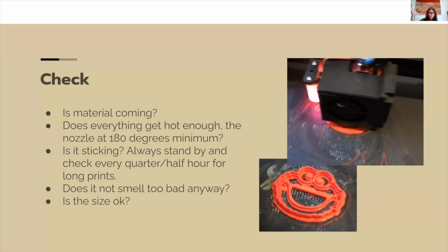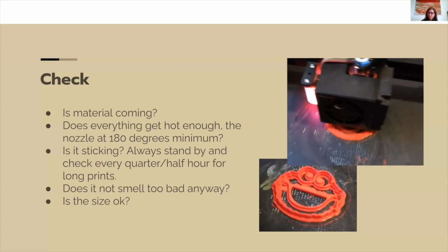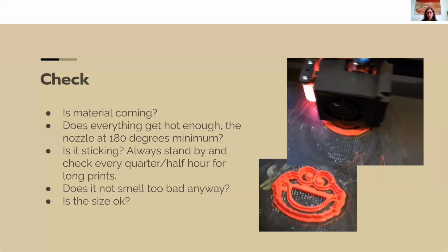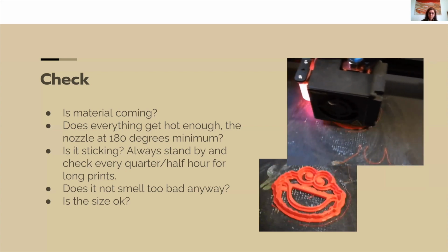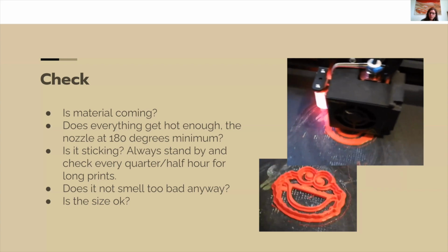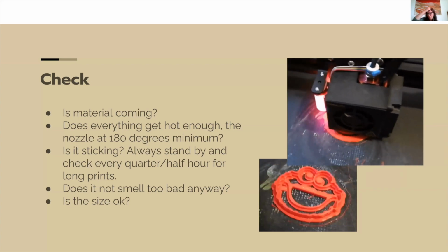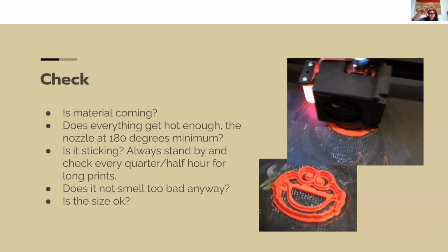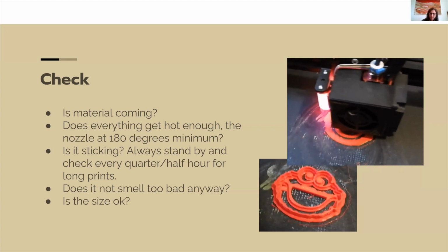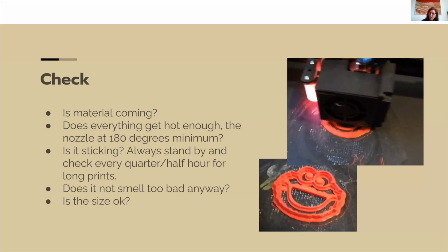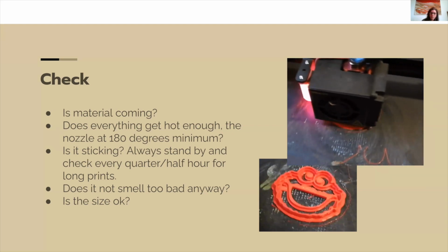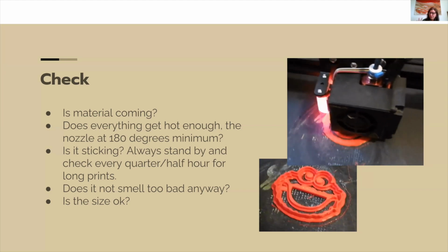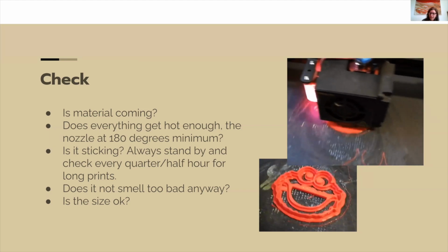Because if you have a print for 3 hours and you leave, and after 2 minutes the material is no longer flowing, you have the machine in use for 2 hours, but you didn't print anything. Is everything hot enough? It should be at least 180 degrees, the minimum at the nozzle. Is it sticking, or is it just not properly working? Does it smell really, really awful? Then you probably have a temperature problem also, or the filament, so the material got dirty and you should change it.